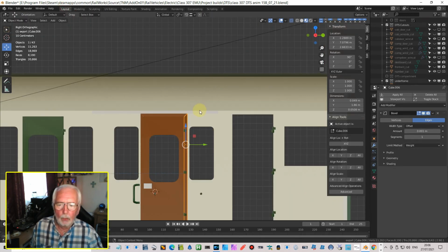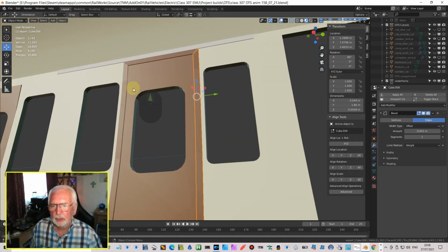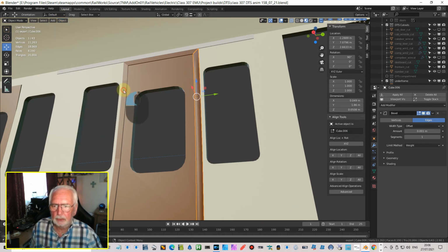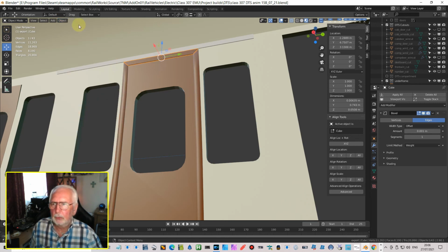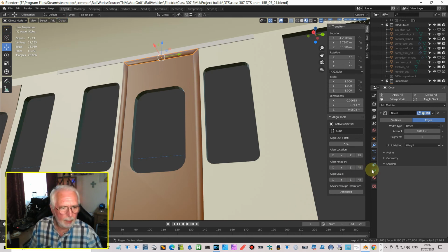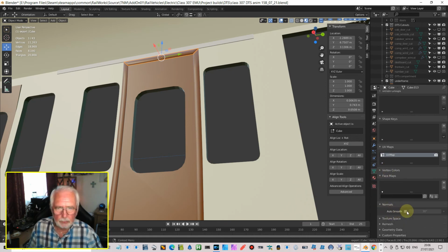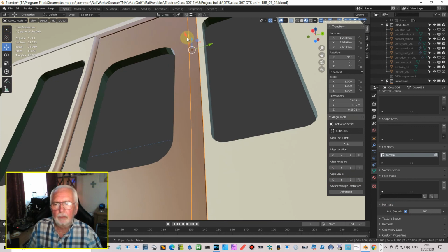Let me come into layout. Where we've turned to match the curve, it looks a bit squarish. So let's just then put shade smooth and shade smooth on those two. There we go. And I suppose we could put shade smooth on that as well. Okay, but now go down here and select your normals and put the auto smooth on. Okay, and that will help give it a smoothness. Okay, but without those harsh edges, or without too much roundness.